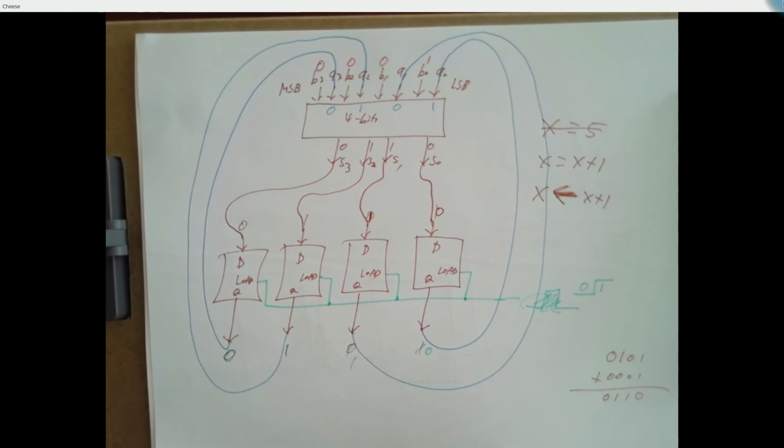Yeah, you can put LEDs, or you can put it on a scope, or in practice when you're doing this, there's things called signal analyzers. You probably work with signal analyzers. And they have this octopus of leads coming out, like 20, 30 leads sometimes. You can clip them at all sorts of different points in your circuit and say record, and it'll record all the ones and zeros at these places, and then you can play it back and look at it different ways.